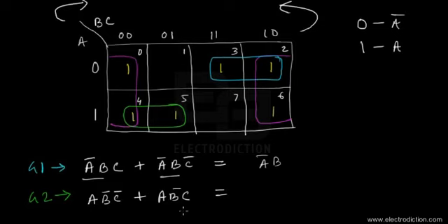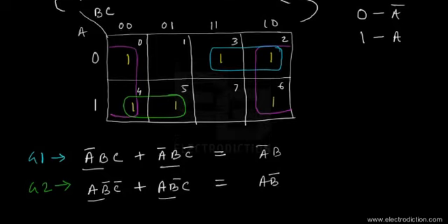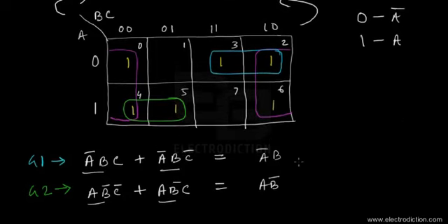If we examine the min terms closely, we can see that we have A B bar common in both the terms. So we take A B bar out, and whatever remains inside is reduced to 1, and multiplied with A B bar yields the same result. This is reduced by the basic laws of Boolean algebra once again. We're not elaborating the process here, as it would just take more time.